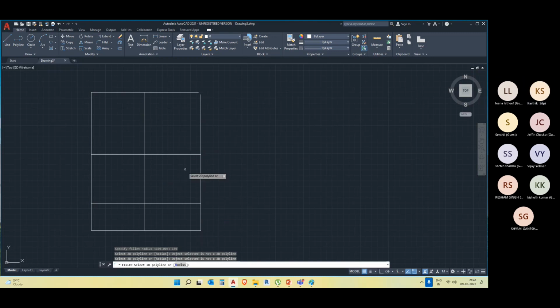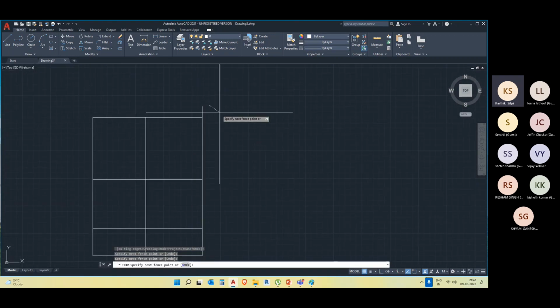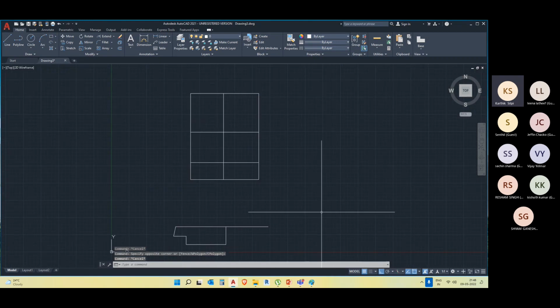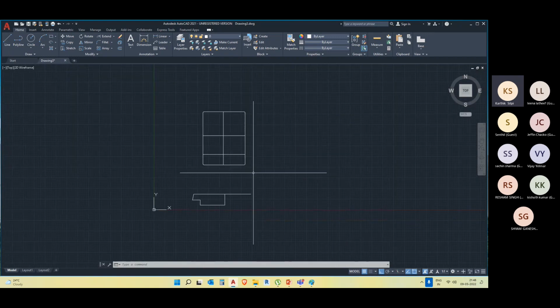It's not a polyline. That is why it is not showing, right? First of all, if you want to have a polyline, I'll just press F5. It's like this. Make this go, so each and everything is an individual element. I'll just press J, enter. Now let me try this fillet polyline. Now let me give a radius of 150 mm. As soon as I pick any one particular instance, you can see the fillet is applied throughout the whole juncture. So that is an advantage of polyline.